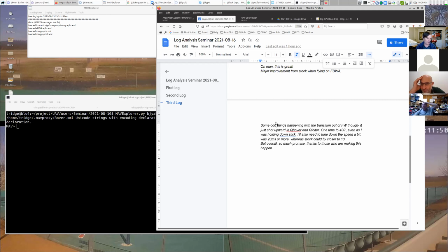Now, you somewhat do expect that. If you've got an aircraft, a tail sitter that's going in fixed wing flight forward, right? And then you put it into a vertical flight like that, it's got a whole lot of kinetic energy, right? So, you know, half mv squared, so its velocity squared is your kinetic energy. And you're wanting to get it into hover where it's now just sitting there still vertically, right? Well, that kinetic energy has got to go somewhere. It could go into noise and, you know, drag and heating the fuselage, but not much is going to go there. Nearly all the energy is going to go into potential energy, and it's going to climb, right?